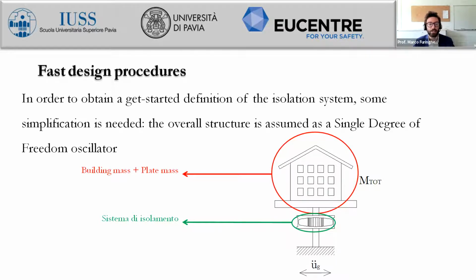As I mentioned in the previous lectures, we will see at the end of this short course that this assumption, that is, considering the overall base isolated structure as a single degree of freedom oscillator, does not lead to significant differences with respect to the real response of the overall system, as returned by a more detailed analysis, for instance, the nonlinear time history analysis. We will see a comparison in the last two days of this short course, where we will compare them.